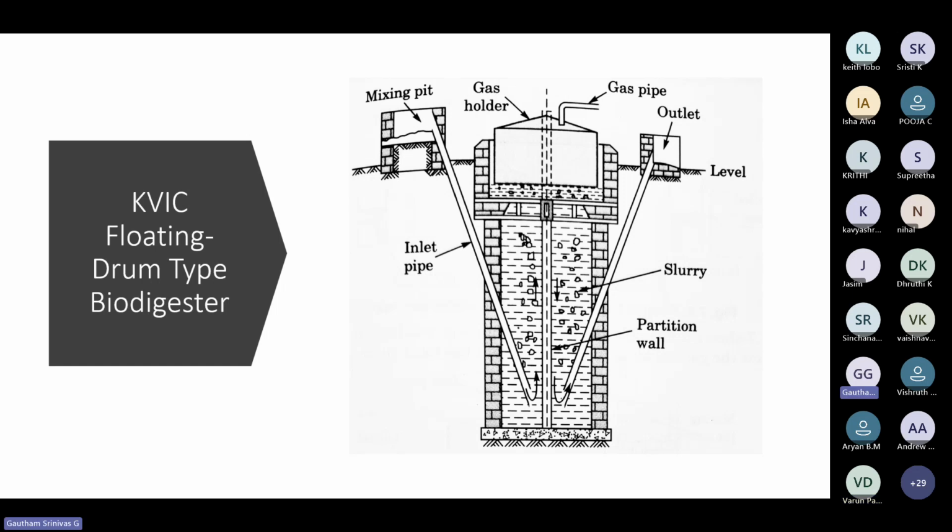This might also be done because, naturally, the gas has to move up, but just to aid in it, so that the gas automatically moves up. And also as a partition between the two stages, instead of making a two-stage design like we saw in the previous slide, with separate digesters for acid and biogas phases 2 and 3, we just separate it.